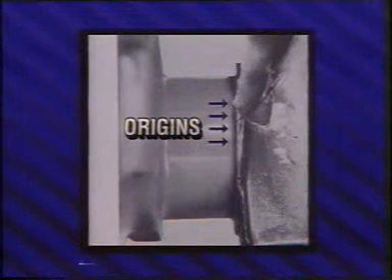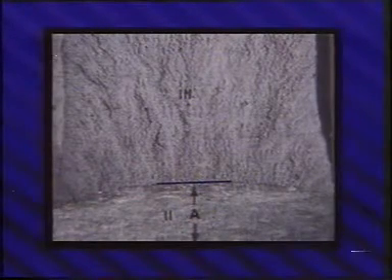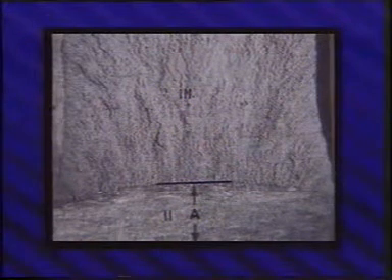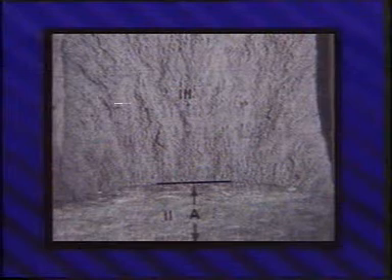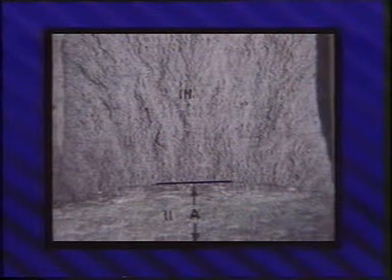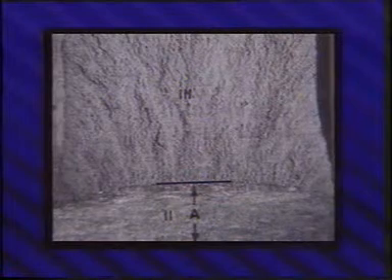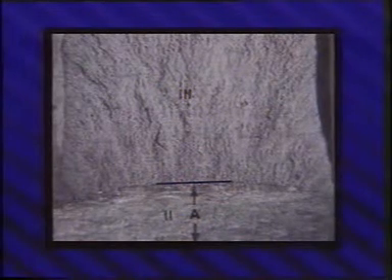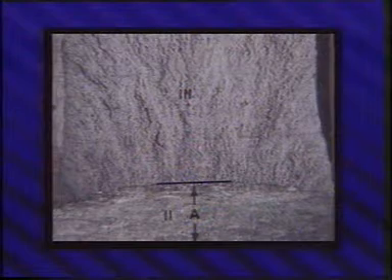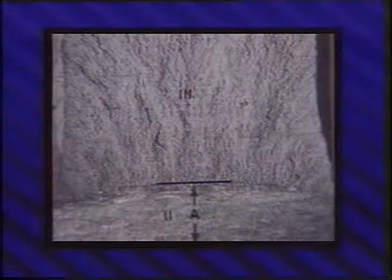Under conditions of uninterrupted, constant amplitude loading, beach marks will not be evident. This fracture surface of a specimen tested in a laboratory shows the load was repeated at the same magnitude and without interruption until the final fracture. The fracture surface produced by the fatigue contains no beach marks. This condition is common in continuous laboratory fatigue testing or in continuous service.